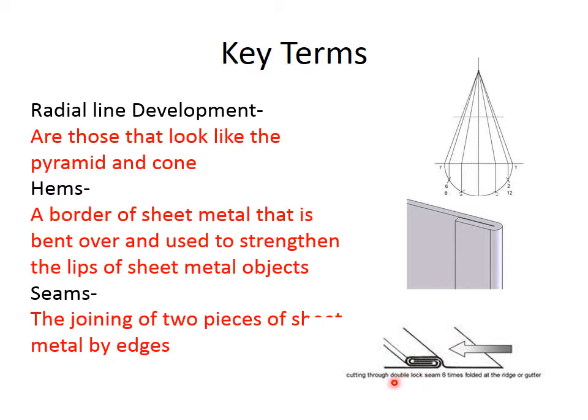Then the other piece of metal comes down, around, and locks through here. A lot of heating, ventilation, and air conditioning technicians put ductwork together using seams. You're not always going to have a piece of metal that's big enough, so you will have to seam those together.